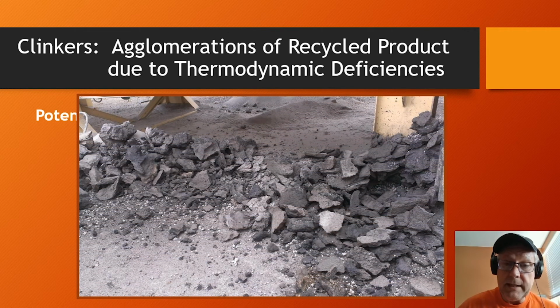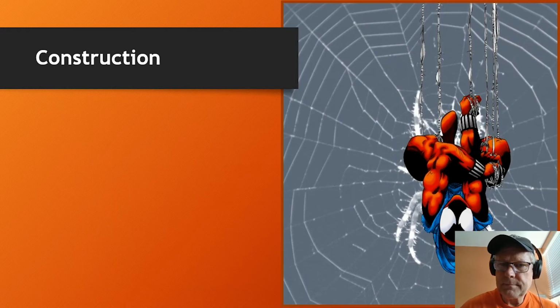This is clean out of a drum after a few days of production. So some people have found out they have to clean out more often than they want, and that leads to vibrating the drum, adding chains, doing something that knocks it free so that you don't get that type of an accumulation, because you certainly shouldn't have to clean out a drum every few days. And again, if you don't clean it out, it'll eventually calve off and end up in the asphalt roadway. And again, we want it to be a uniform mixture that's placed out there.